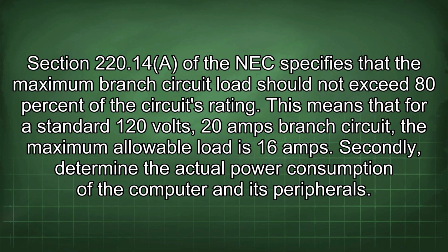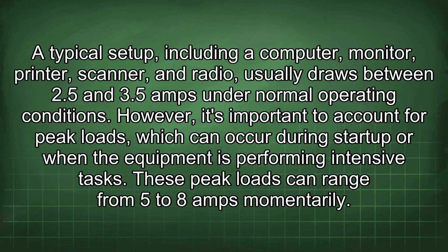Section 220.14 of the NEC specifies that the maximum branch circuit load should not exceed 80% of the circuit's rating. This means that for a standard 120 volts, 20 amps branch circuit, the maximum allowable load is 16 amps. Secondly, determine the actual power consumption of the computer and its peripherals. A typical setup, including a computer, monitor, printer, scanner, and radio, usually draws between 2.5 and 3.5 amps under normal